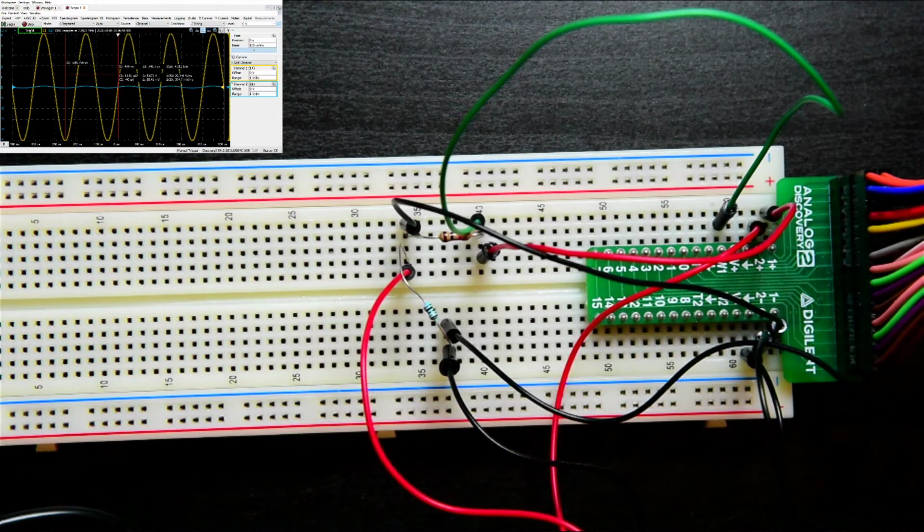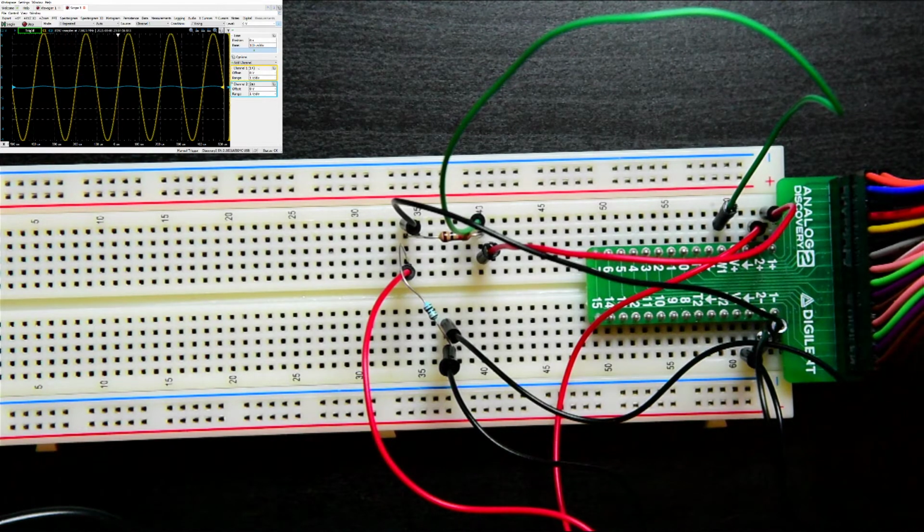use the two scope channels to measure the voltage across R1 and to measure voltage across R sense. Alright, and run the WaveGen tool in waveforms to enable the AC voltage source and use the scope tool to display the voltage across each resistor at an appropriate scale. So let's change the scales.